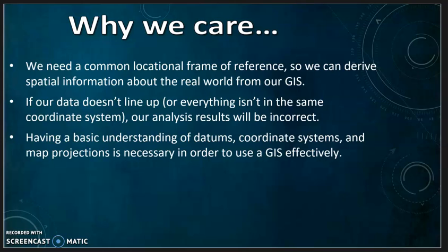One of the biggest problems you're likely to encounter, especially early on, is that your layers aren't going to line up. A rivers layer for Humboldt County here and a roads layer for Humboldt County there. Not always that obvious, and you may not even notice. And you'll start to understand this a little bit more later, but all the layers might be in Universal Transverse Mercator, but they're in a different datum.